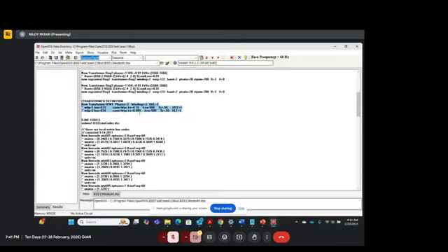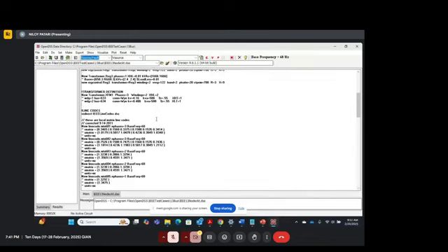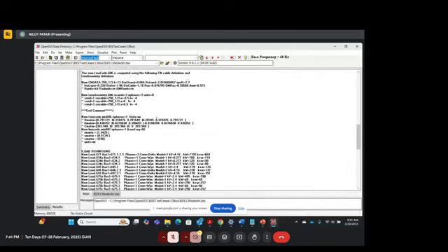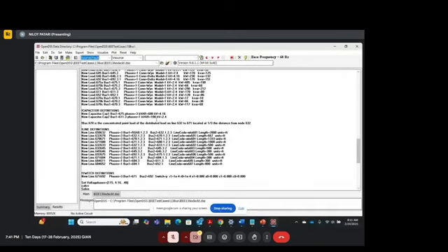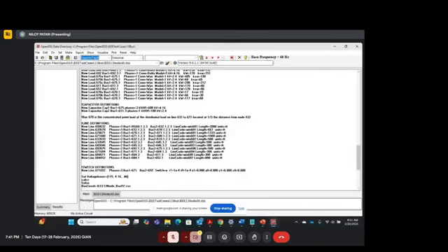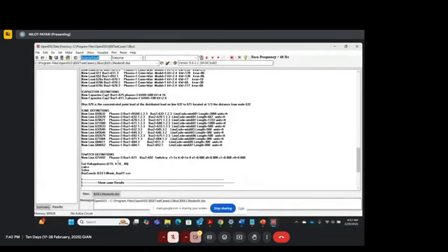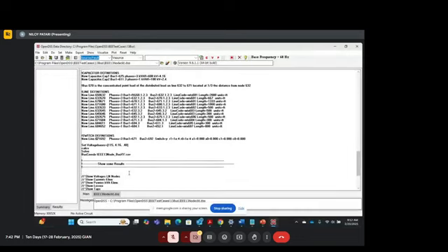If you model 10 houses in OpenDSS and connect them to 480 volts, you can say this is a 13 bus feeder I've created in the secondary distribution feeder, connected from the house transformer to 10 houses. You have to define voltage bases, because if you don't, OpenDSS cannot convert to per unit form. Then you have CalcV. What Solve does is that it solves the power flow.